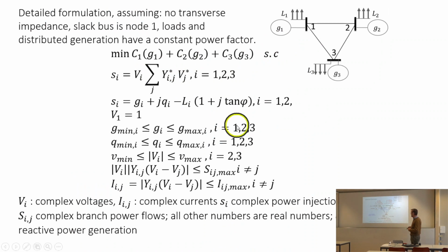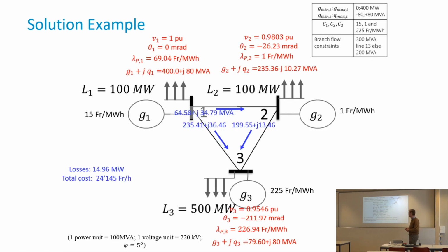If you remember, in my assumption, I was assuming that the loads are not purely active power. They have a reactive power component. That's typical of all electrical machines. There's another source of reactive power, which is the lines themselves. The lines have inductance, also sometimes capacitance, or both, or one dominates the other. So in either case, they generate or consume reactive power.